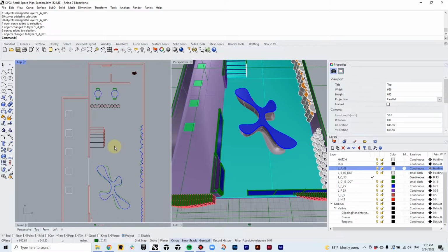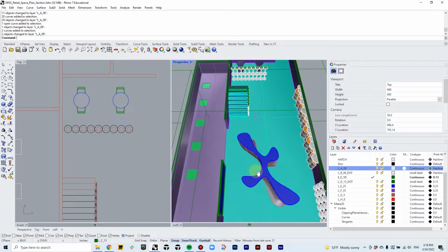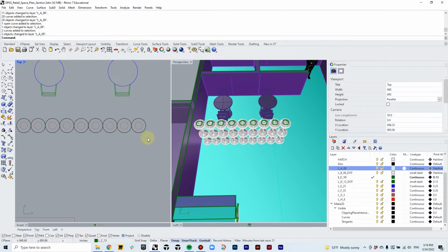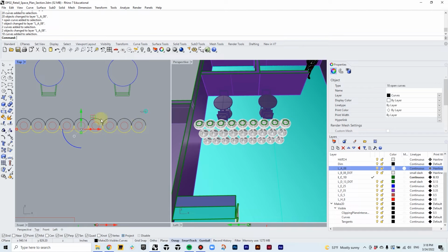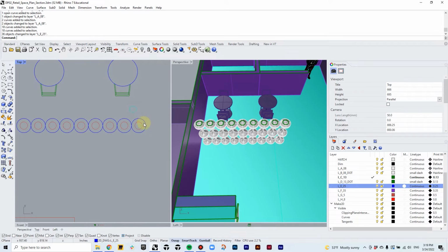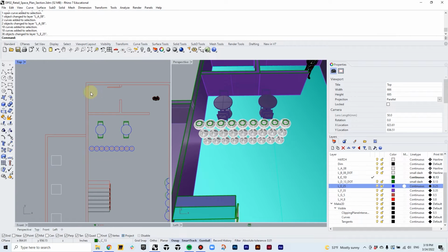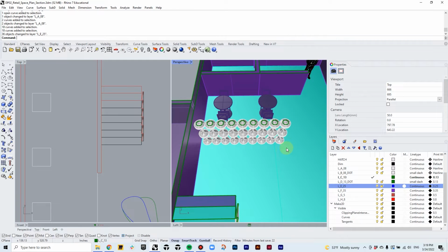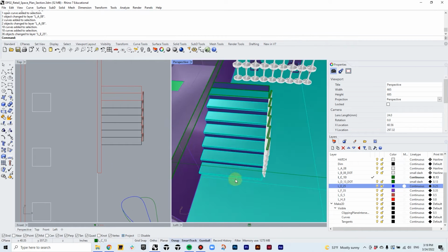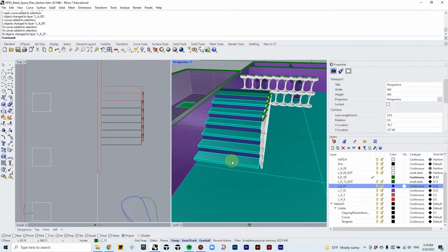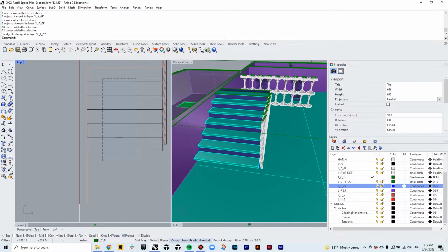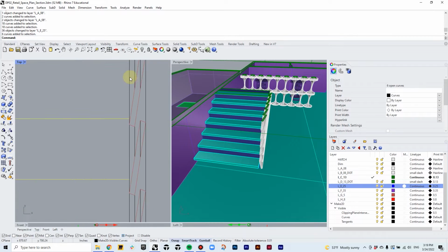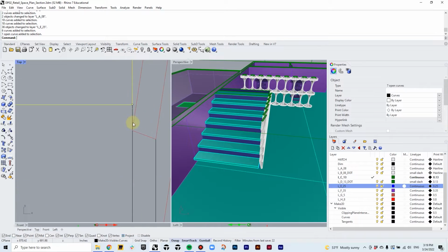So now we are, oh, and then also these guys which are here, those are pretty close to the view, so I think they can be 0.25. Okay. And yeah, we can just draw toilets and stuff later. So the stairs are kind of tricky because they start somewhere really close to the ground, and then it ascends up. So in this case, we are going to just assign the green layer to it.